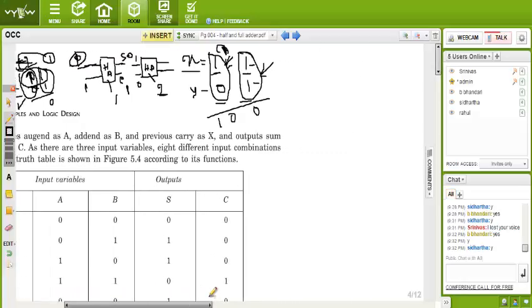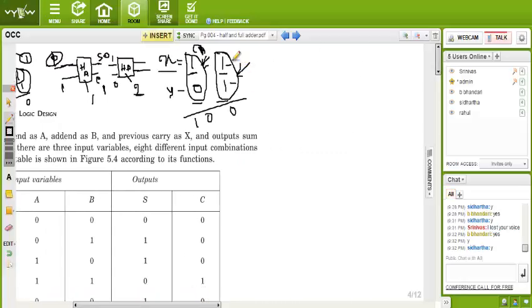Okay. Now see, this is the LSB, least significant bit, and this is the MSB, most significant bit. So in decimal addition, we start with the least significant bit. We start from this side, right? So we take a half adder and do the least significant addition of 1 1. This 1 and this 1. Then what will be our sum and carry?